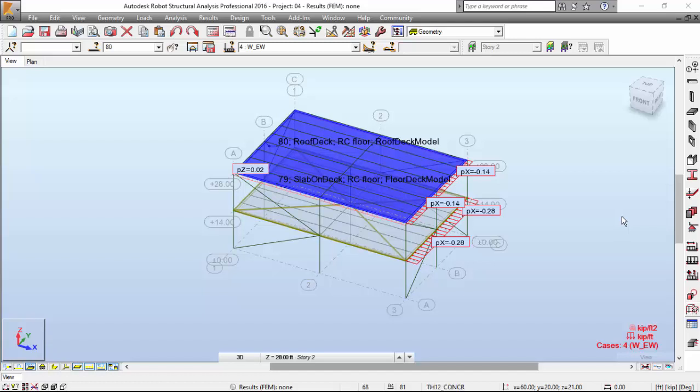So now let's do it. Let's configure the basic seismic load. We will use the equivalent lateral load seismic load from the analysis types menu. So I'm going to press this button over here.